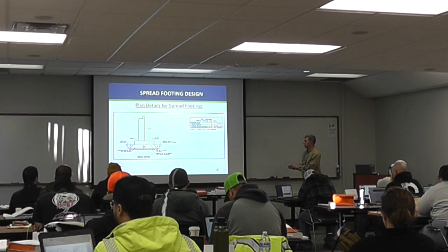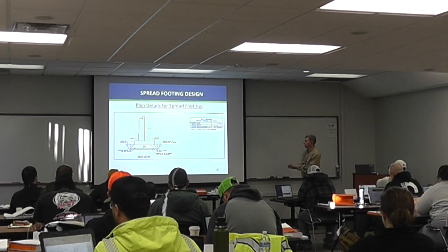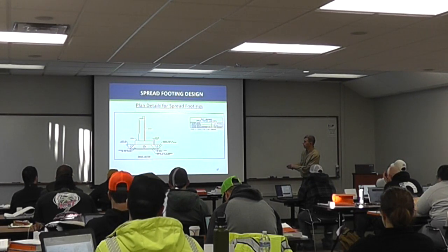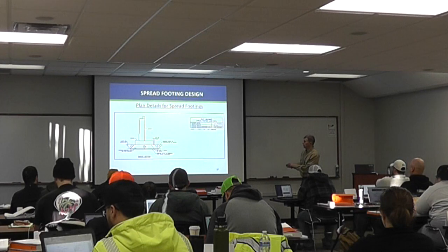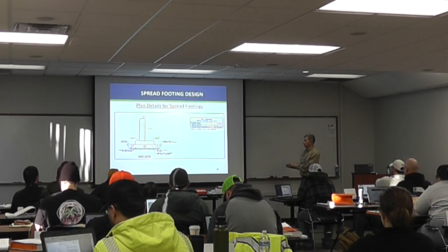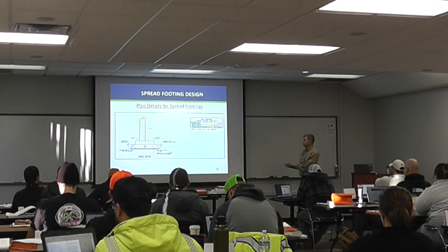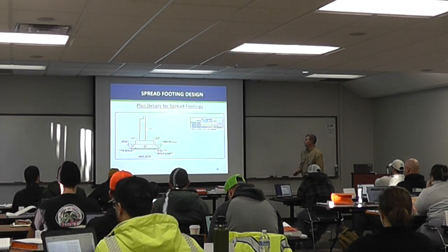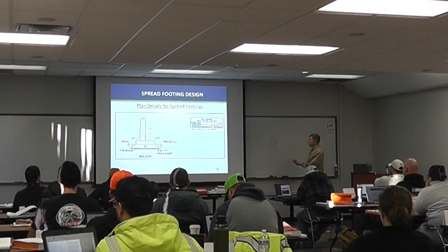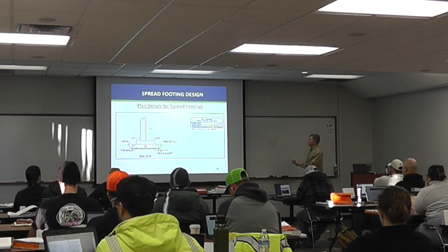This would say here, compact the top 6 inches of the subgrade, and this one is talking about aggregate backfill underneath the footing. So in this case, they actually dug out some of the material, put back different material, and then the bottom of the footing is right there. And here we see again a table of data: factored bearing resistance 3.16 tons per square foot.